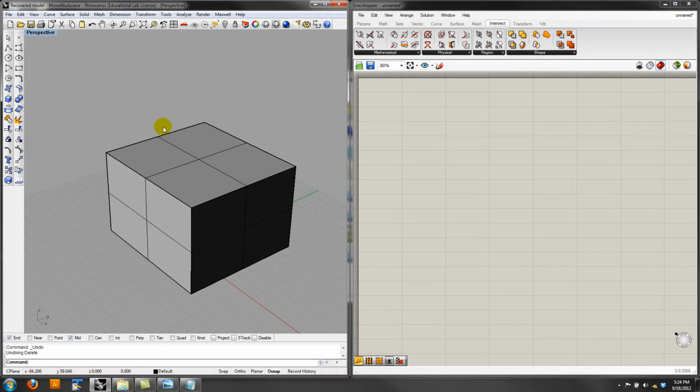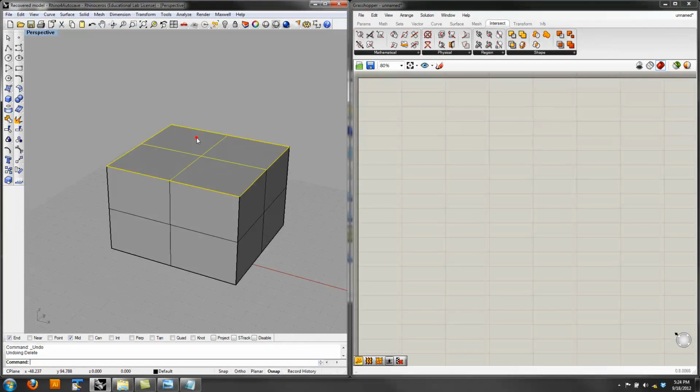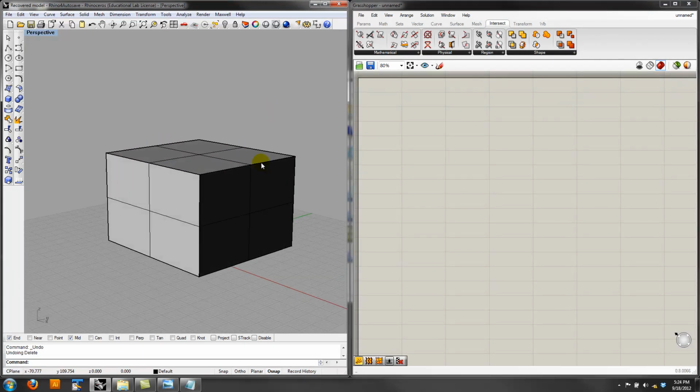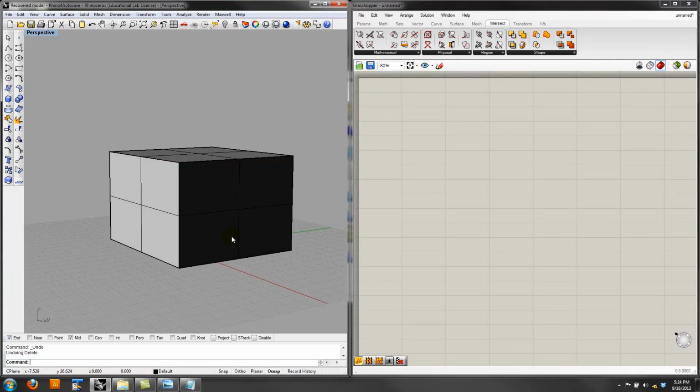It's like because sometimes you want to take a form that you already have, that's something that you modeled in Rhino, and break it down so that you can get access to curves on that surface, and then use those curves to find points, and then use those points to distribute some geometry. Or start from a series of points and work your way all the way up to your final form.